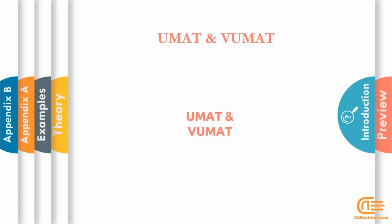We define the material using the UMAT and VUMAT. What does that mean? What we are doing in these subroutines is to redefine the relation between stress and strain for Abaqus, but in a way other than the methods of the Abaqus material library.